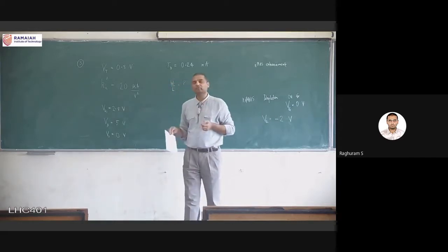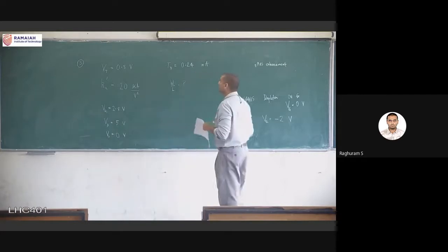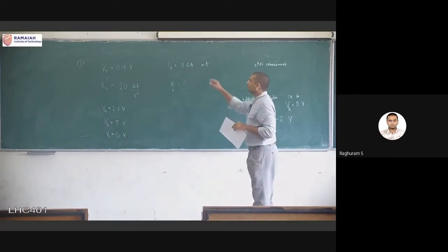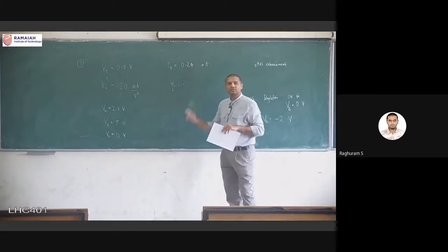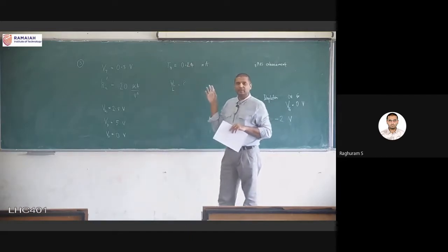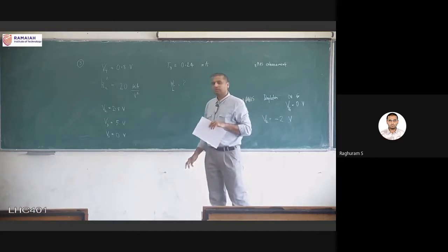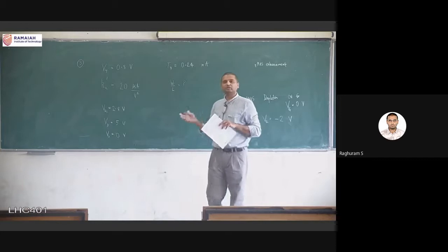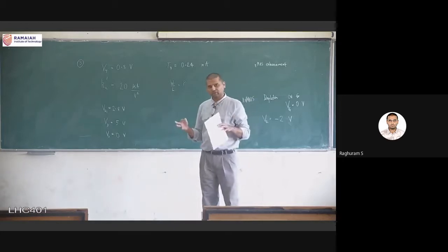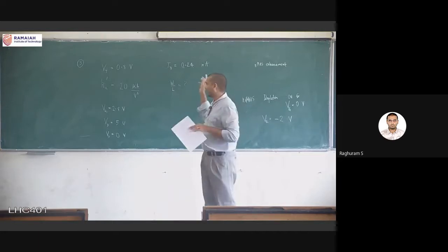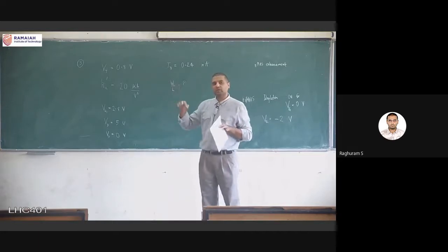So we have to look at the operation and find out what is the region of operation. Linear, it's definitely on because it's quite a big current, 0.24 milliamperes through a single transistor. Okay, so once we find out what is the region of operation, then we have the equation. So from that equation, we have the left hand side. Generally, we are trying to find out the current. This time we have the current. We have to solve for the W by L.